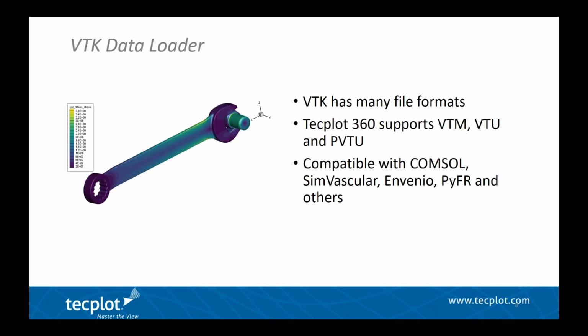So if you have a code that is running distributed on an HPC, it may write out a portion of a zone on each rank of that HPC. And then a PVTU file is going to give instruction for how to stitch all of those pieces of a zone back together to create a single zone.